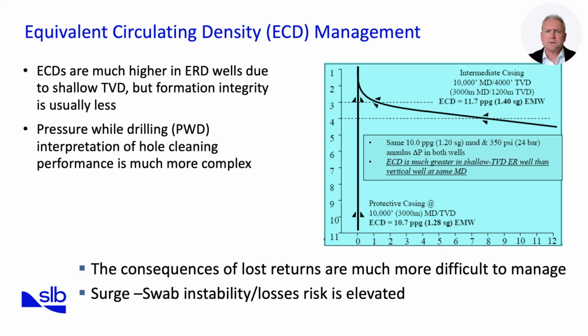In other words, when the TVD is shallow, that pressure loss represents a bigger percentage increase in ECD. This is because of the growth of the frictional losses in the annulus from cuttings beds and eccentric flow. This causes the ECD to climb more rapidly, resulting in a narrow mud weight window for operation. Next, we'll see how trajectory design can be optimized to help manage these pressures.